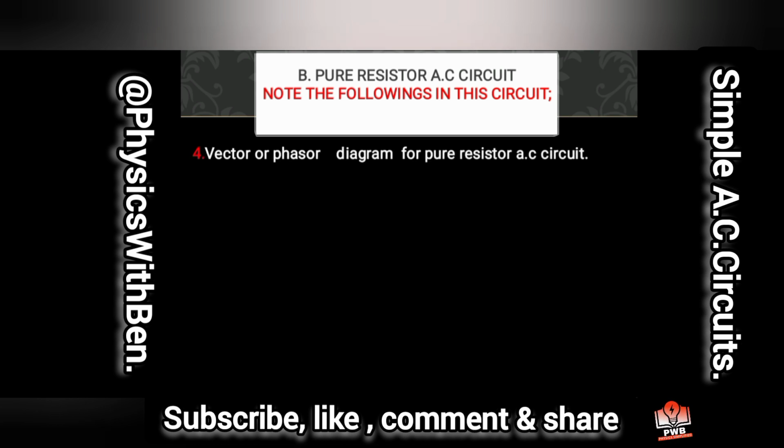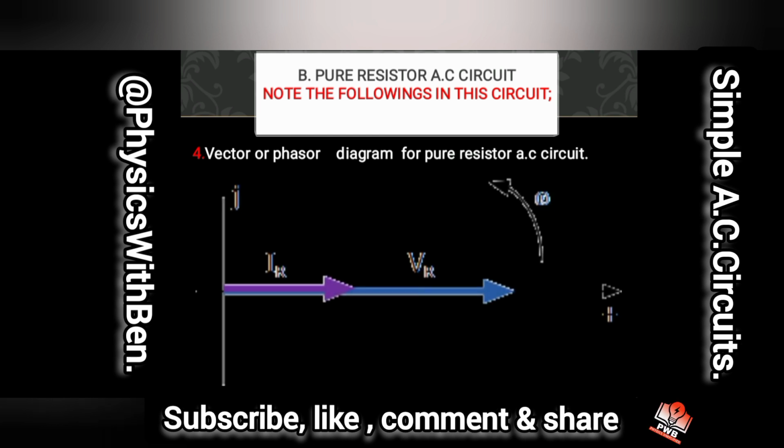Next up, the examiners may ask you to draw the phasor or the vector diagram. Very, very important. And this is the phasor or the vector diagram. Here is angular frequency, not written in bold letters. And here is the current IR and then VR. So you see the arrows facing in one direction, meaning they are all in phase.